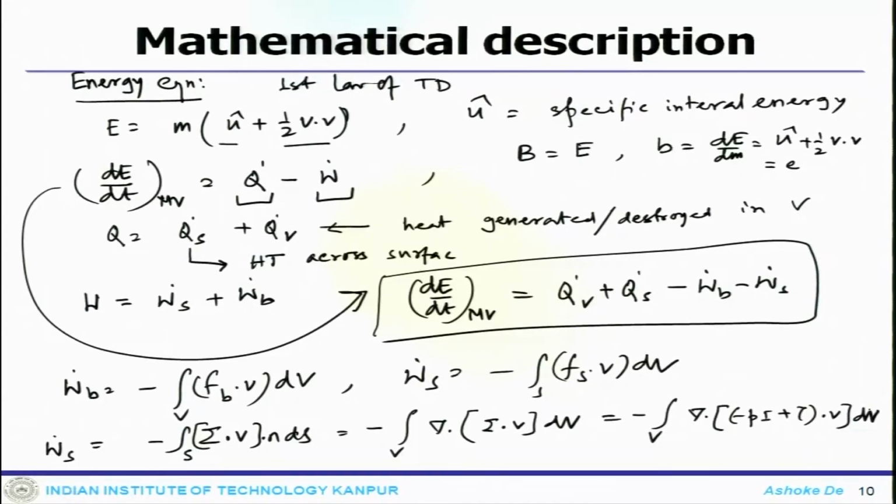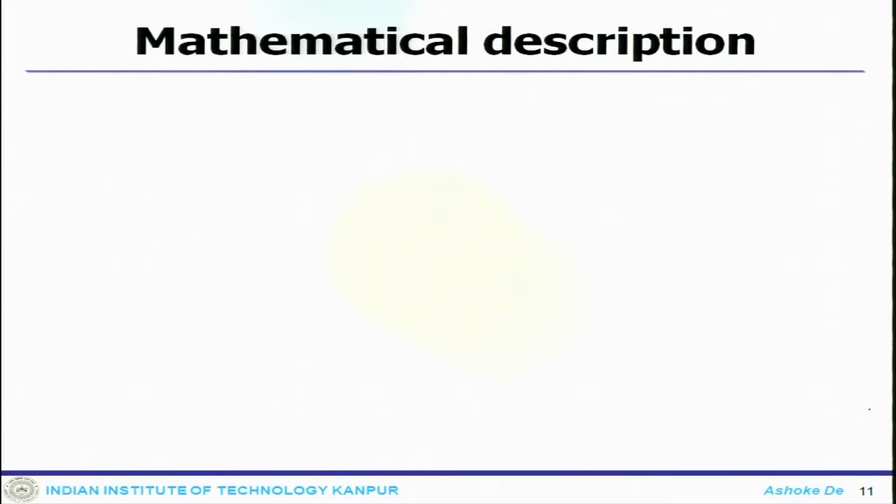So, this is my surface force. So, if I write it back, the work done due to surface force is nothing but the integral over V of minus del dot P V plus del dot tau dot V dV.